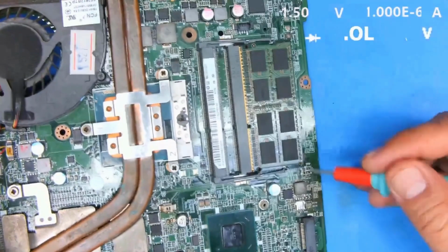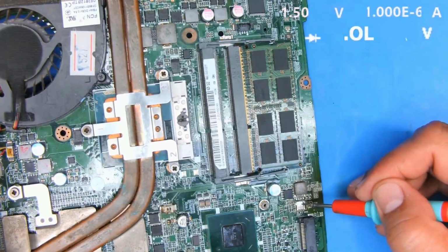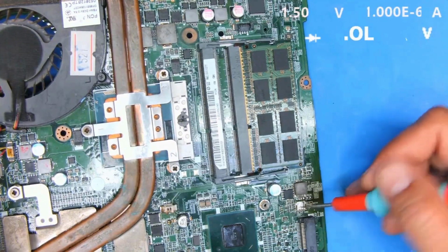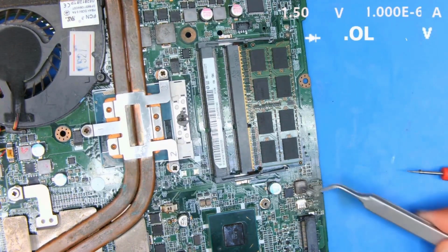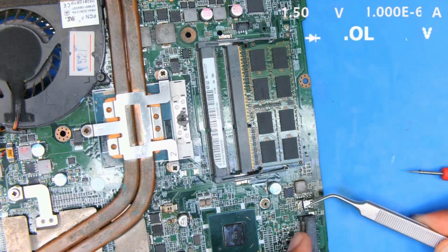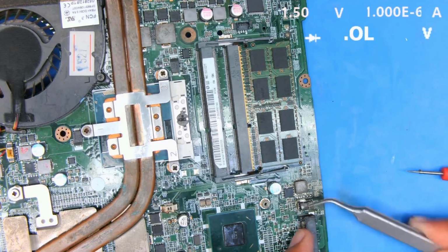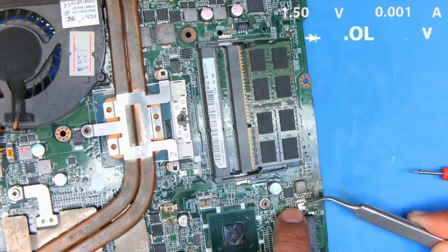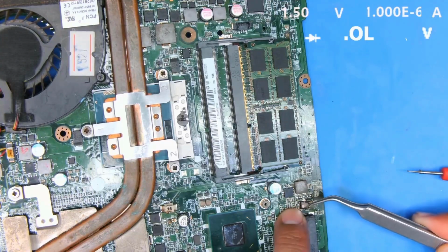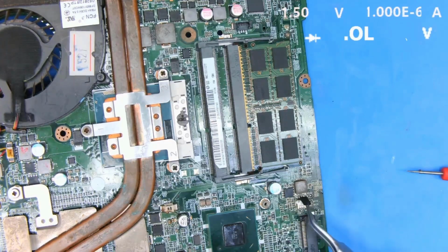We found that the MOSFET was faulty, so now we'll replace it with a new one. If we don't replace this part, the power supply won't work. You can't just refresh or reset it. You have to replace it. In newer models, the casing is designed so you can't put the part back in the wrong way. See? There's a casing. The casing has a full leaded PCB pattern like this. When you turn it this way, you can't insert it backwards.